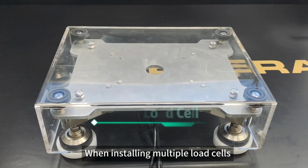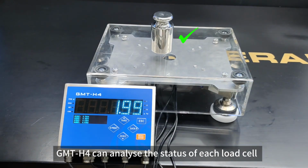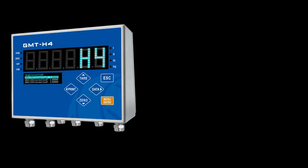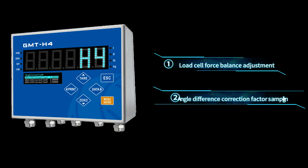When installing multiple load cells, we need to make sure of the balance and minimize the scale angle difference. GMT-H4 can analyze the status of each load cell and determine whether the force on the load cell is even or not. There are two steps of adjusting the angle difference by GMT-H4. First, load cell force balance adjustment. Second, angle difference correction factor sampling.